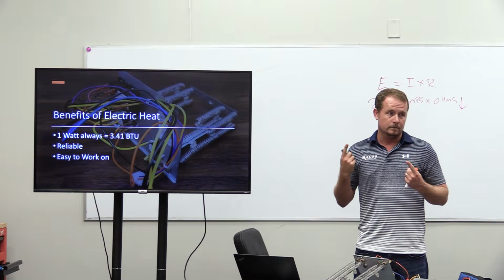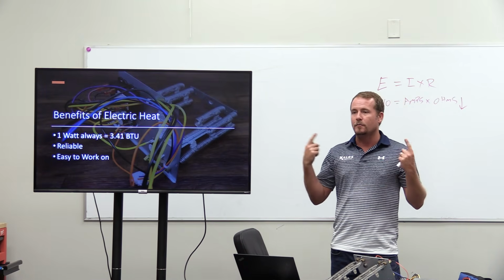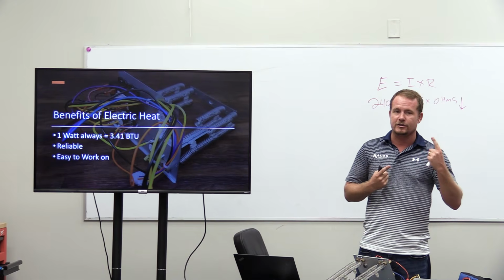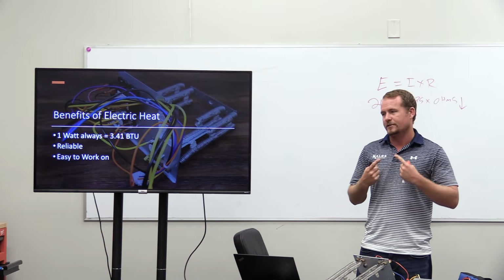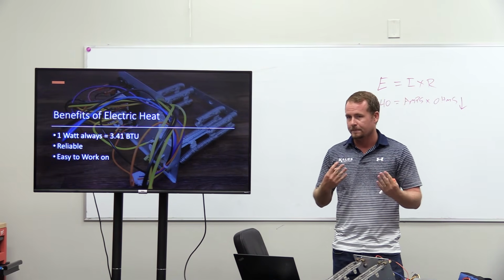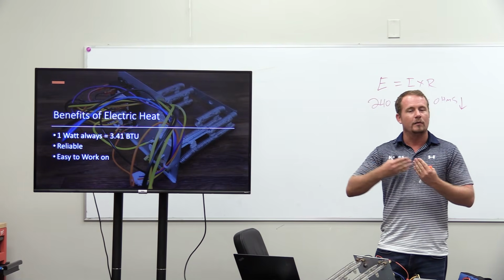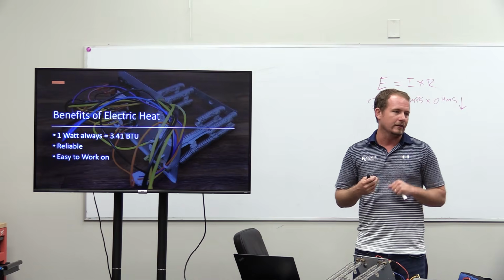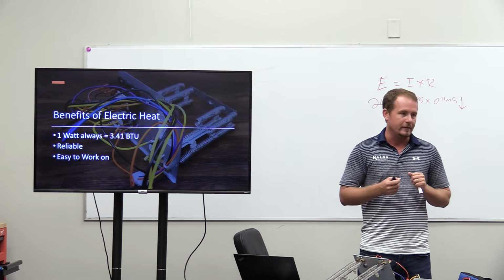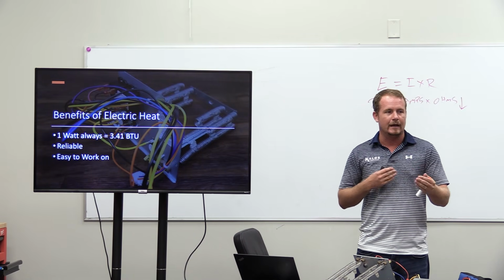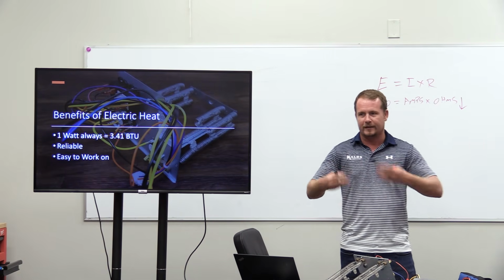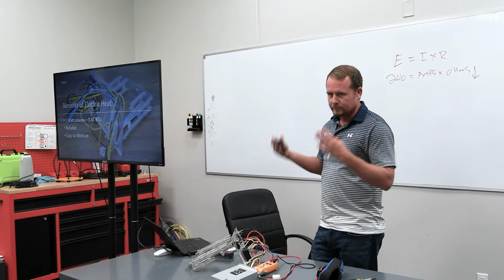Just that simple. And so if you've ever heard of COP, coefficient of performance, COP is a measurement where you compare the efficiency of a refrigeration device or some other device that moves heat around to electric heat, and it's always more efficient. So a typical COP for a pool heater, for example, would be like a COP of 3, which means that it's 3 times more efficient under normal operating conditions than if you were just running electric heat to heat the pool. Make sense?